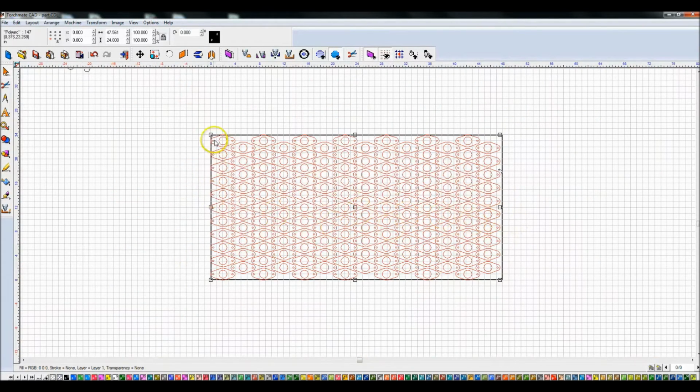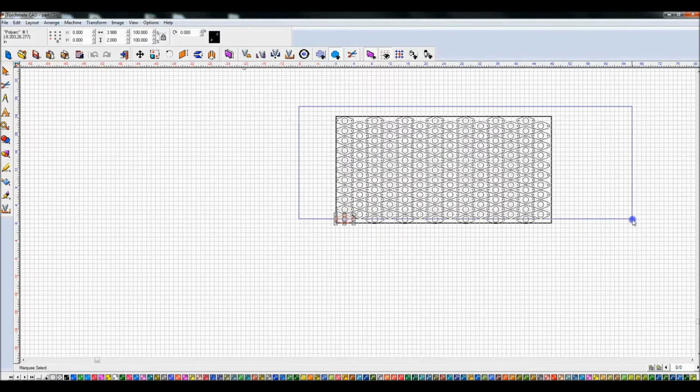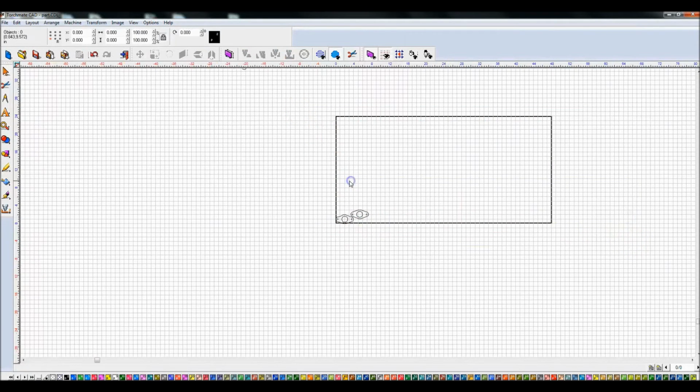Again, I would probably create the toolpath on one of these and then tweak the toolpath. For instance, I'd want a pierce point in this area instead of right in between these two parts, which is what happens sometimes. So I would create a toolpath on one particular piece. Let me just do this real quick. We'll just do a meld toolpath.